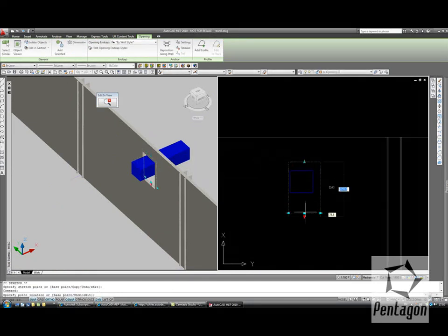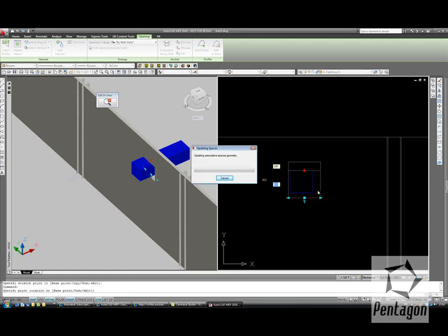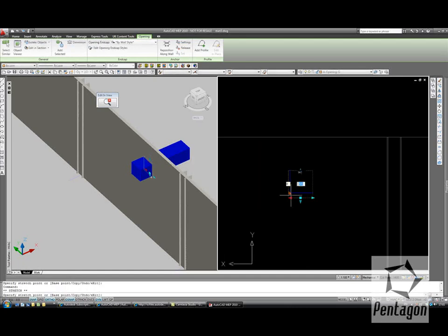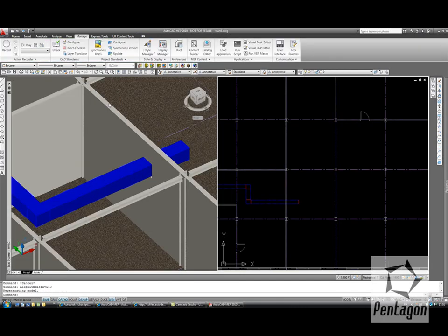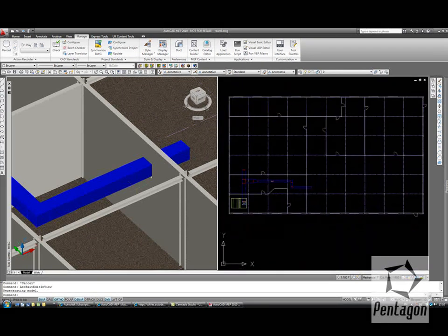I've got many components in the library I could add in, like my fire dampers or fire cutoffs, as well, but I'm simply just going to tie it in against the actual ductwork, maybe with a bit of a gap for working, and quit out back to my view. So very easily we can add ducts in, modify the duct positions and elevations, but work with the architectural components